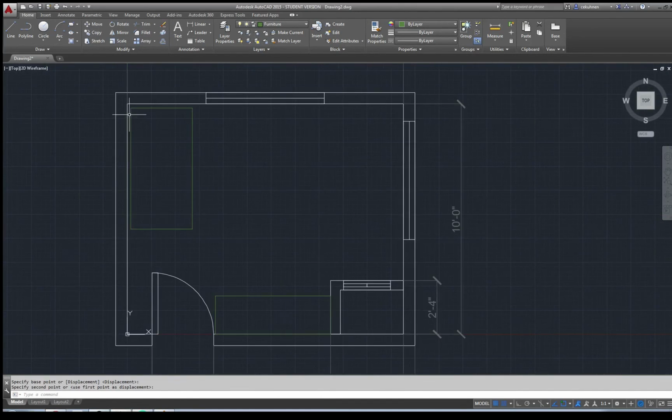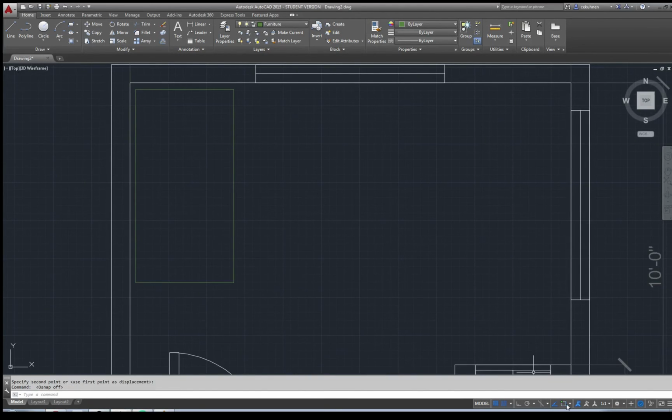So I will go ahead and say move this object, spacebar, this corner to this corner. Great. And maybe let's move this computer table onto this wall. There, and it didn't snap, because the snap settings got confusing, so I turned all this off. Let's turn nearest on. Click spacebar.